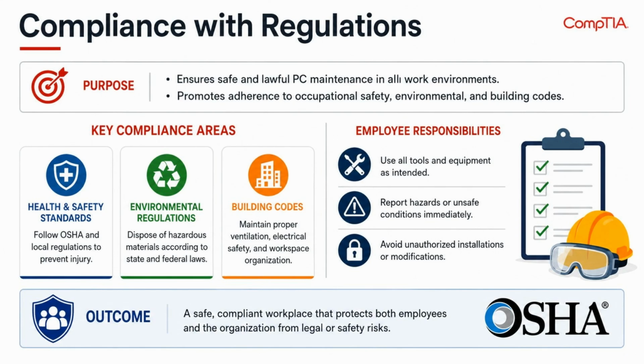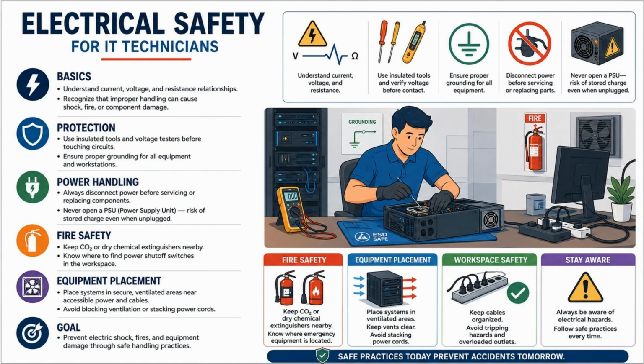Employee responsibilities. Use tools as intended, report hazards immediately, and avoid unauthorized installations. The outcome: a safe, compliant workplace protecting both employees and the organization. Understand the relationship between current, voltage, and resistance, and recognize that improper handling can cause shock, fire, or component damage. For protection, use insulated tools and voltage testers before touching circuits, and ensure proper grounding. Always disconnect power before servicing, and never open a power supply unit. There's risk of stored charge even when unplugged.